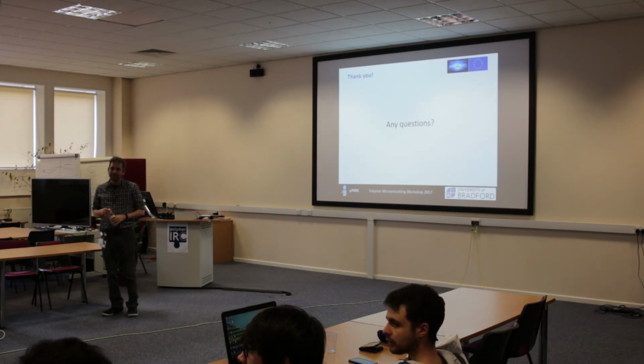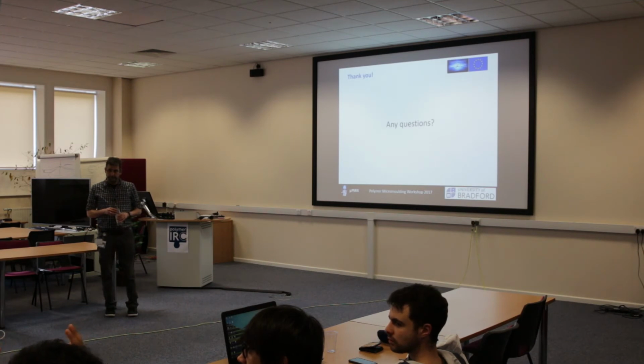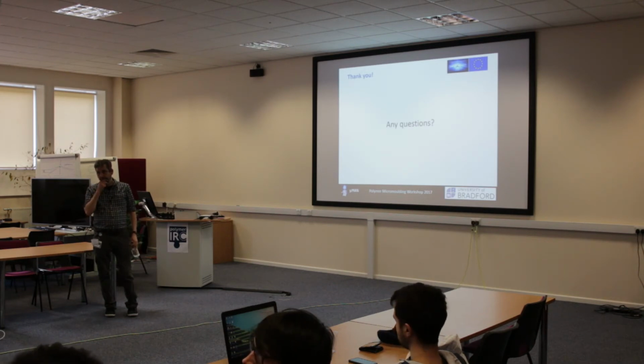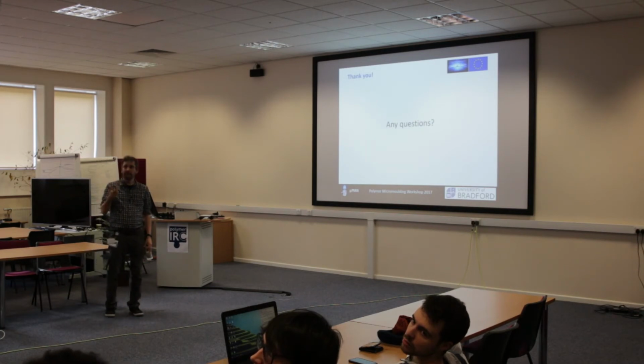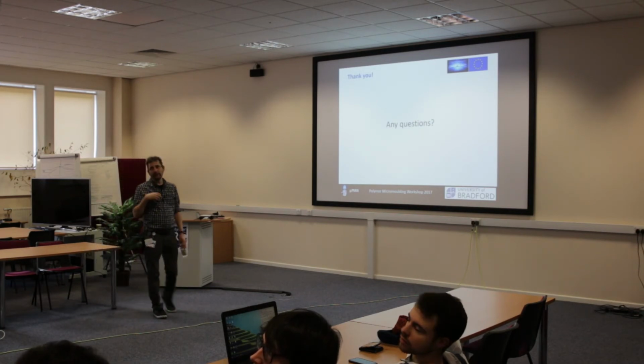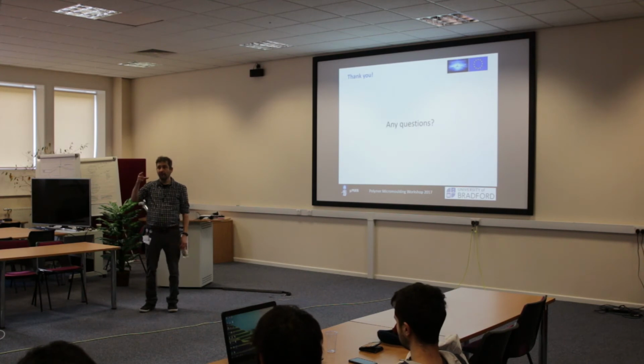But for PET it is not a problem, but for something like ABS or EVA, when you go to process in the filler there, they have the heating to keep it warm. Otherwise they absorb the water and cannot process. Yeah, so it's case by case for materials. Normally you will have nitrogen blowing continuously. For PET microinjection molding, you will have dry nitrogen out at the top.